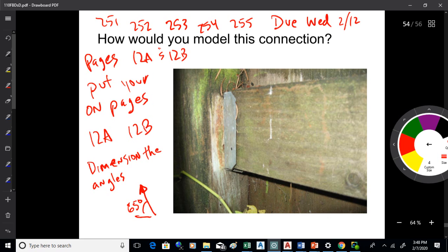If it's reaction forces, like you said about a pinned weight, how they have the y direction reaction force, do we have to draw that at 90 degrees both ways? They should be 90 degrees apart from how you draw them. I don't think it cares if it's exactly 90 degrees. If it's close and I can look at it and say it's 90 degrees, we're good.